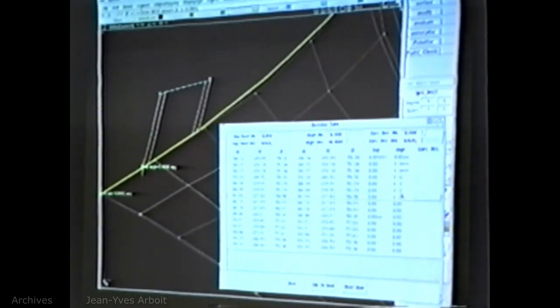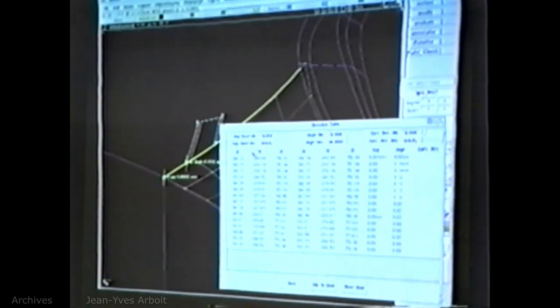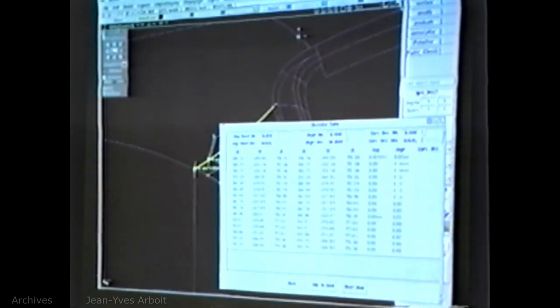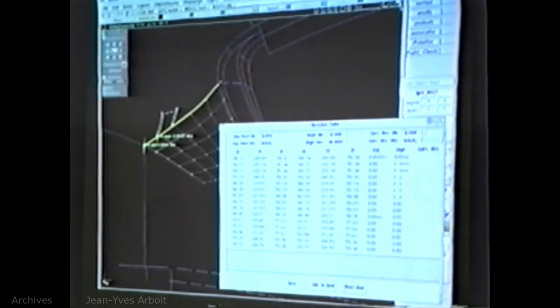So as I move and scroll here, you can see where those positions are on the object, and that'll work for both tangency, deviation from scans, and curvature as well. And then if my deviation's here between 184, if I put this at an angle minimum at 0.5, and then set that at 0.1.